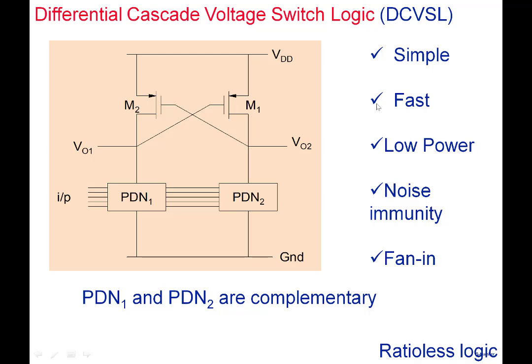And so they're eliminating the power by adding this. But then in the process, what did they lose? The simplicity. Whatever was here, they replicated another part here, two pull down networks. So I would put a question mark here. It doesn't retain the simplicity of that other one.